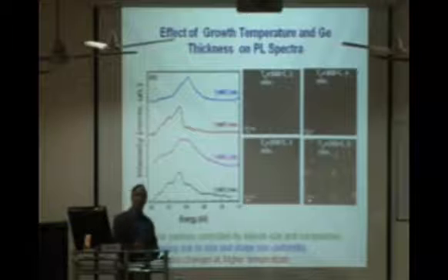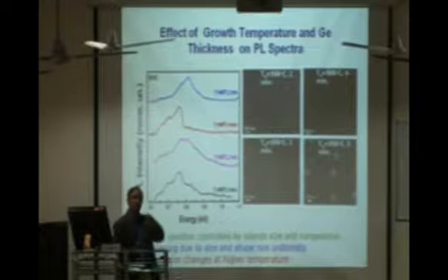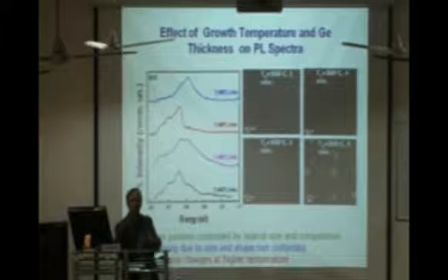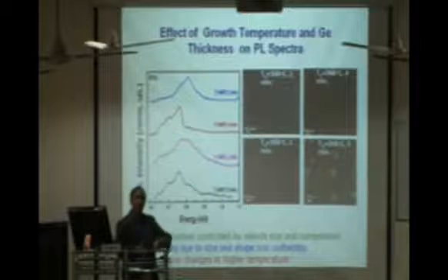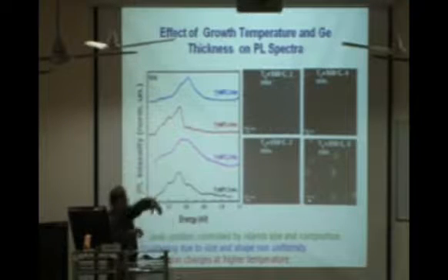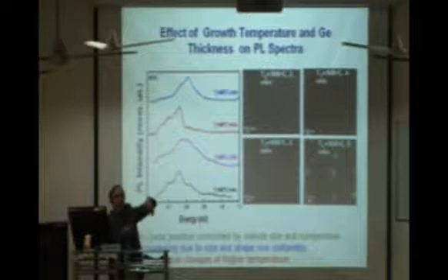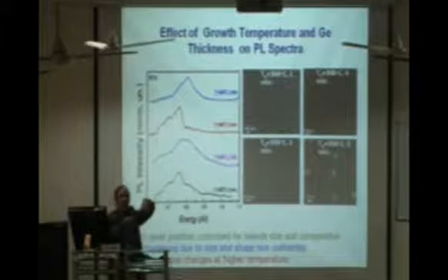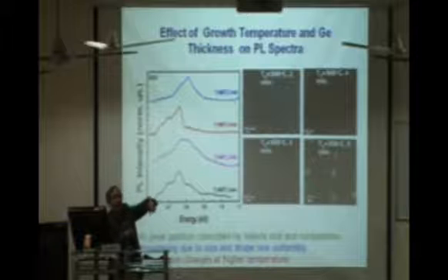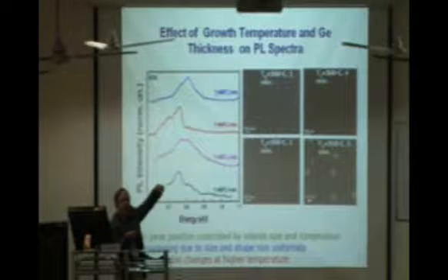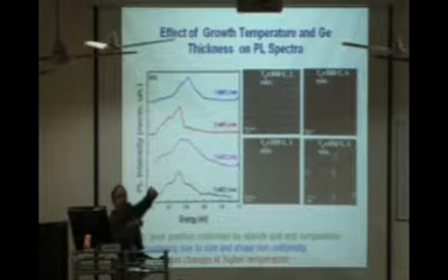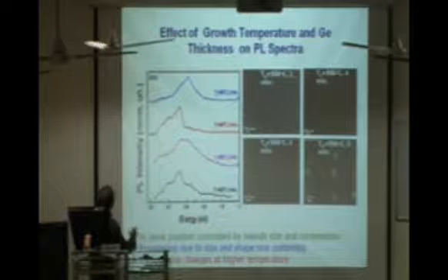So the first observation, whether they are really quantum dots: as I said, we don't get any light emission from silicon or germanium because of the indirect bandgap. But there is a possibility of formation of excitons. This is a heterostructure, so there is always a band alignment, a band offset in the conduction band and the valence band offset. Holes are typically confined in the valence band, and the electrons are localized in the conduction band offset. So there is a strong overlap of wave function between the electrons and holes in this kind of quantum dot, and they can form these excitons.